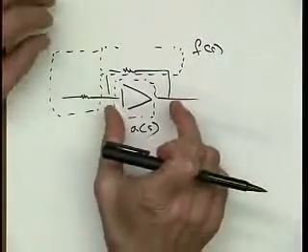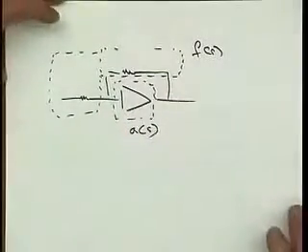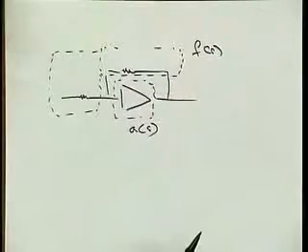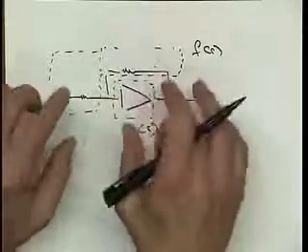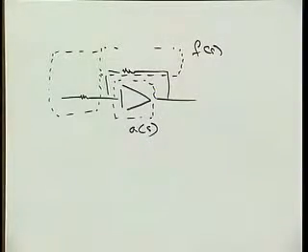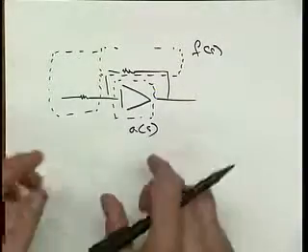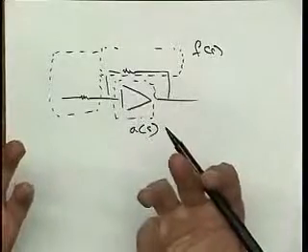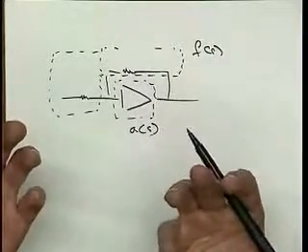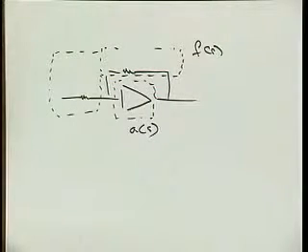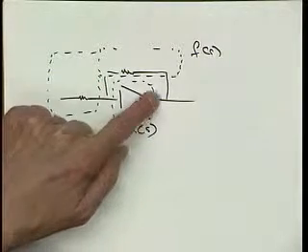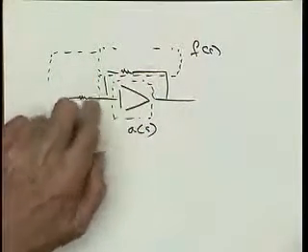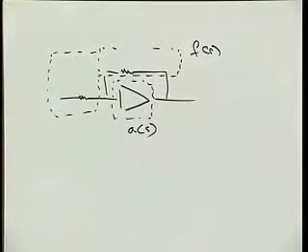Now, when doing that analysis, you mentioned one problem. That is that you have to sort of simulate the loading effects, because the minute you take away this network from the feedback circuit, then of course the amplifier sees different loading, and it may behave differently. Now again, if it's operational amplifiers, then that's probably not too big a deal, because the output impedance here is very low, probably low compared to the loading from the feedback network. It kind of doesn't matter.